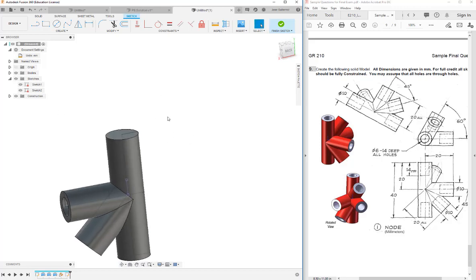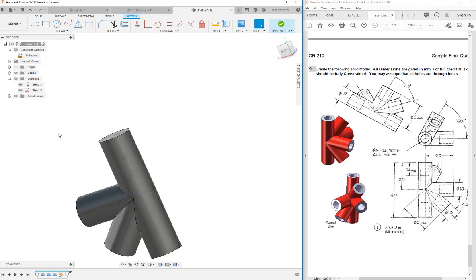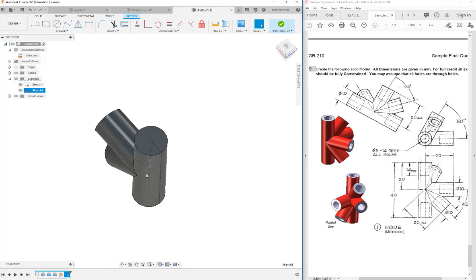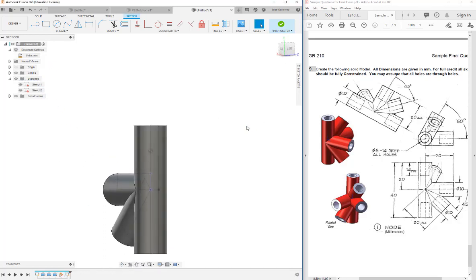And the reason I'm going to do that is I want to make sure I'm constraining back to my original origin, not the origin that the sketch over here has decided to define. Okay, and so now I can continue to sketch away. Now, if I like to look normal at the sketch, I can click on it and then say look at. And then now I can go ahead and make my features that are at the angle.